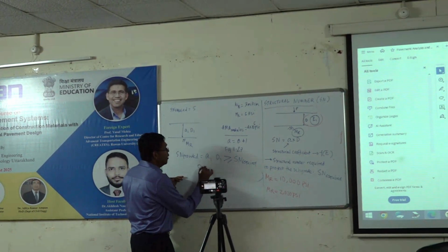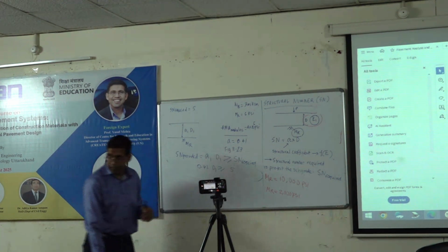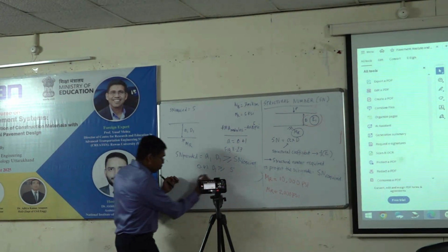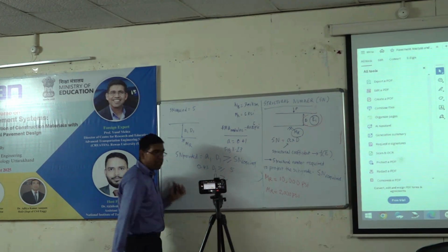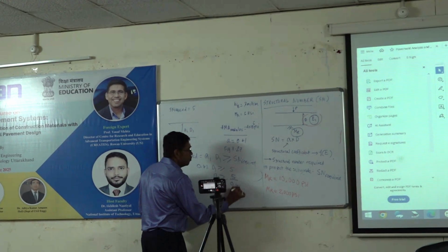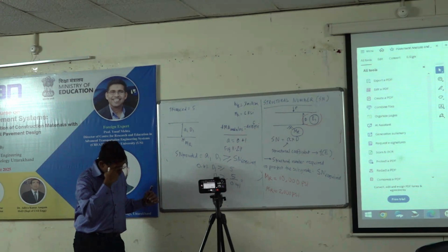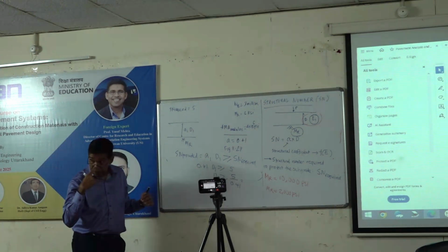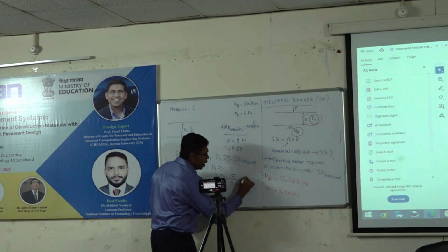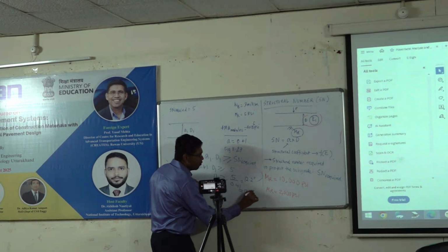A1 is 0.41 times D1, greater than or equal to 5. Right? That's what we got from the previous Sn required of 5, from the nomograph. So my D1 should be greater than or equal to 5 divided by 0.41. Anybody can give me a number? 12.2. 12.2 inches, and I will round it up to the next half inch, 12.5.